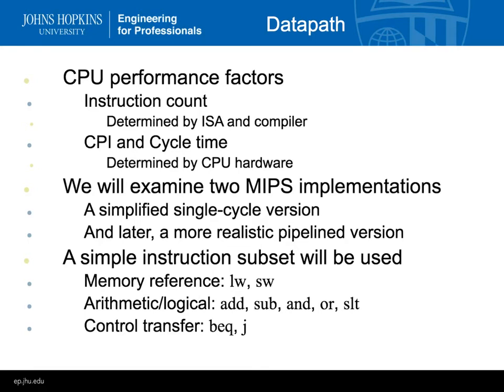And then after that, we're going to talk about pipelined, where the instruction is broken up into multiple cycles, where in each cycle part of the data path is run. But this week we're doing a single cycle where in one cycle the instruction is read and interpreted, and the computer takes an action in one cycle.